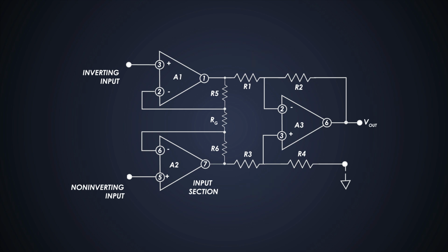If you have noticed, there is one terminal called reference. There is usually one more called sense, but it's not important for now. By using this reference terminal, we can play with the ground connections. It allows an external offset voltage for the difference amplifier where we can change its reference potential. For normal conditions, the reference is connected to the ground.